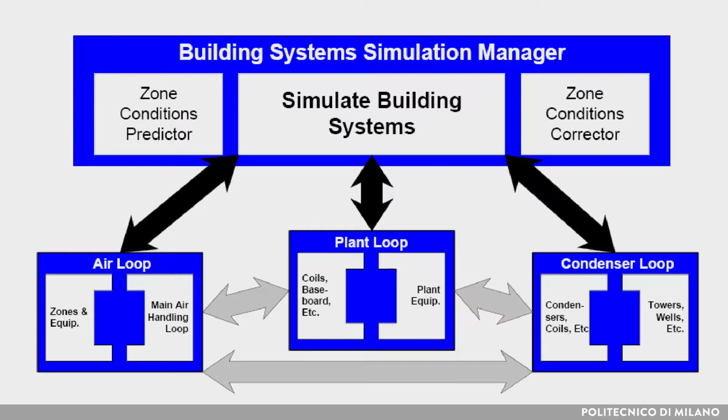Loads, calculated at the user-specified time step, are passed to the building system simulation module at the same time step. The Energy Plus building simulation module calculates the heating and cooling system and plant and electrical system response. This integrated solution provides a more accurate space temperature prediction. Also, it allows users to evaluate realistic system controls, moisture absorption and desorption in building elements, radiant heating and cooling system, and interzone airflow.